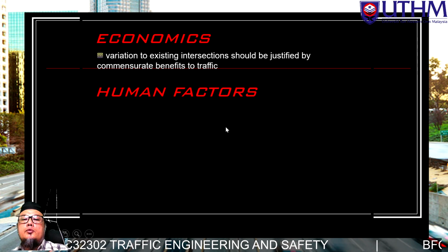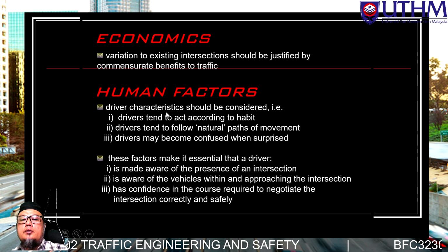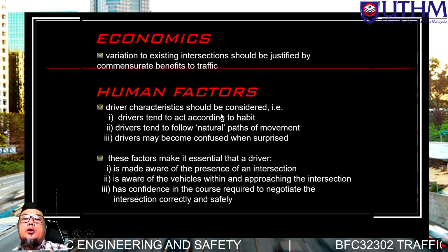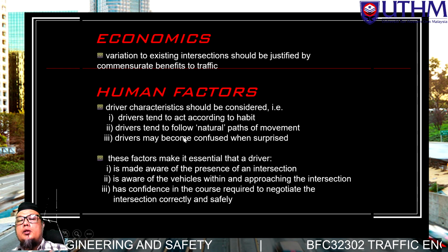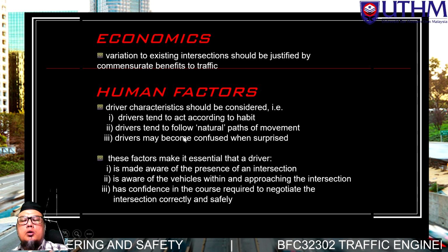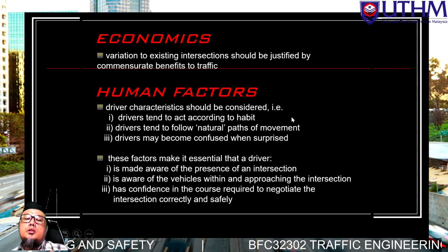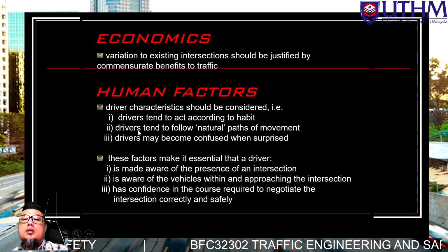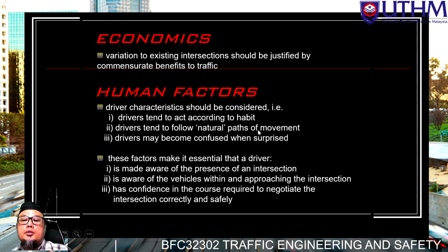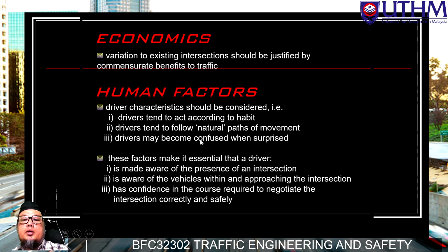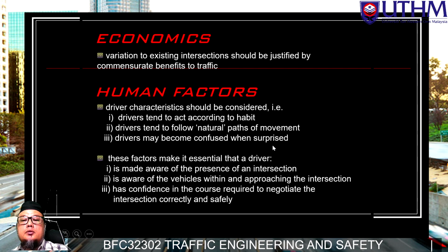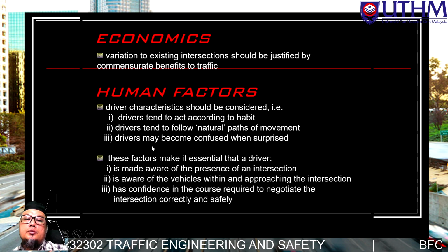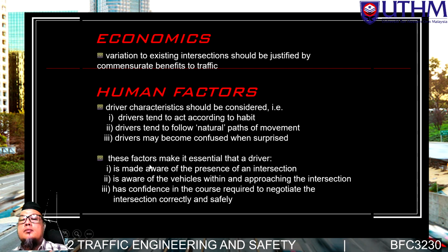Okay, in terms of human factors, the driver characteristics should be considered. Drivers tend to act according to habit, which means the route or alignment should be easy to cope with. Driver behavior or driver tendency: drivers tend to follow the natural path of movement. Drivers become confused when surprised. So sometimes we have to consider this, especially novice drivers, not experienced drivers.